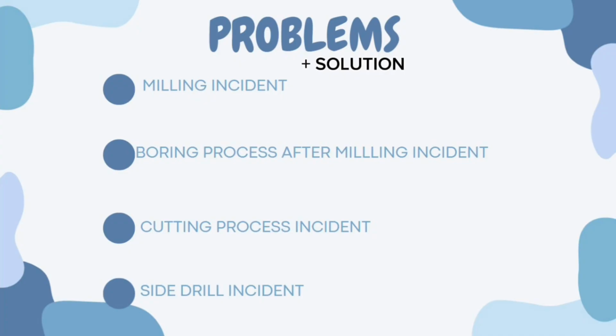The second problem occurred in the boring process, after we realized our first problem. We created a massive material removal at 45 degrees on the inside of our material, which was caused by tool deflection and incorrect feed and speed. We fixed the problem by using a better tool for our boring process, and thankfully we were able to get the dimensionally accurate and precise inside hole for the workpiece.